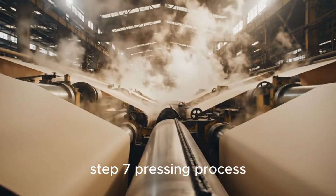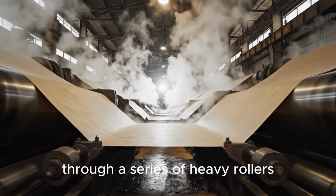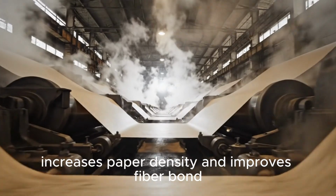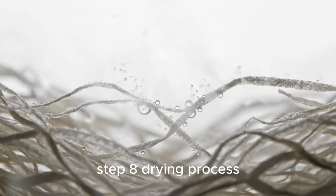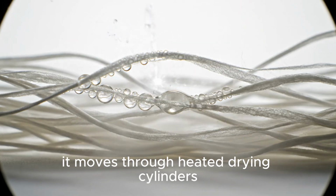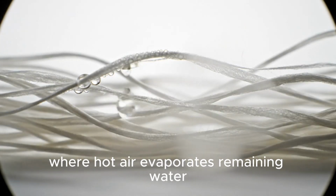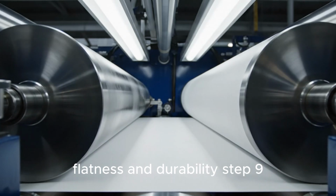Step 7. Pressing process. The wet paper sheet passes through a series of heavy rollers that squeeze out excess water. Pressing increases paper density and improves fiber bonding. Step 8. Drying process. After pressing, the paper still contains moisture. It moves through heated drying cylinders where hot air evaporates remaining water. Proper drying ensures paper strength, flatness, and durability.